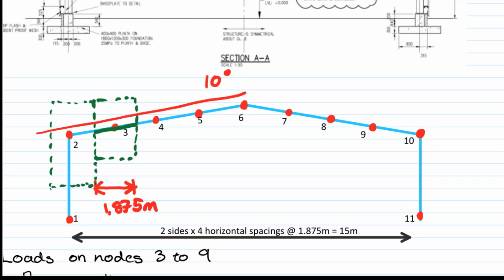And so we're going to have half the amount of sheeting, half the amount of imposed load. If we had a big cantilever on the side, maybe not, but it's roughly half the amount of imposed load. And then also now we have column load, but once again I said column is included in the software, but we do have side sheeting all along here. Actually, let me put this in red to be consistent. So I've got side sheeting, and I had some girts on the side. So I need to add those in.